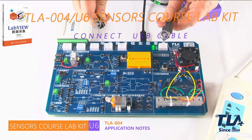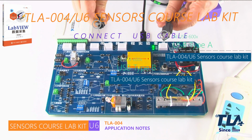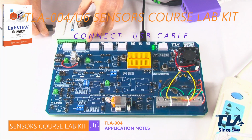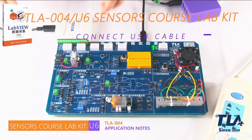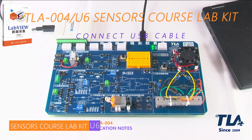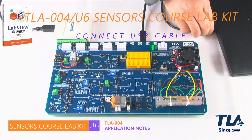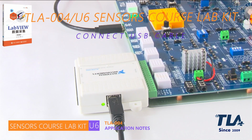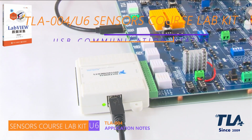Next, connect the USB data acquisition card with the computer. One end is a Type A flat port and the other end is a Type B square port. First insert the square port end into the Type B USB socket on the left side of USB-6009. Insert the USB plug with the flat port at the other end into the USB socket of the computer. This completes the connection between the data acquisition card and the computer.